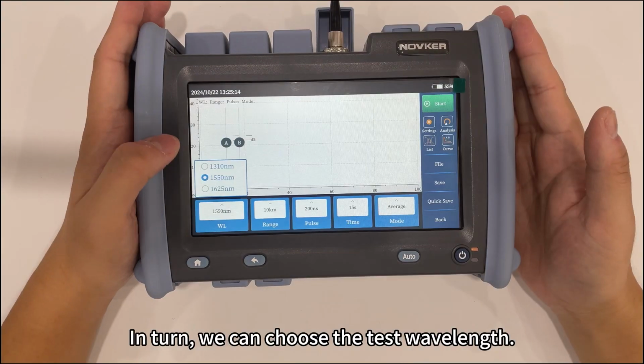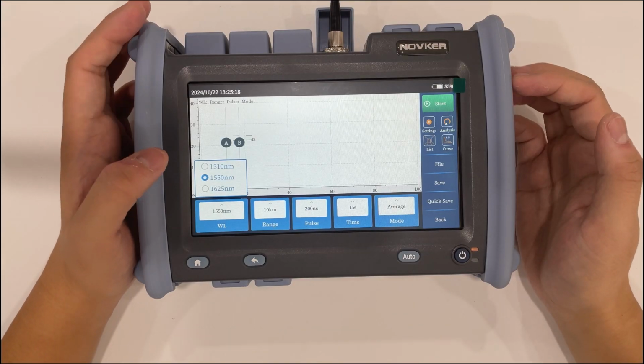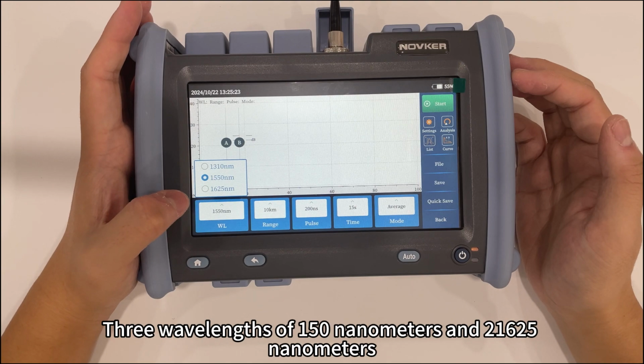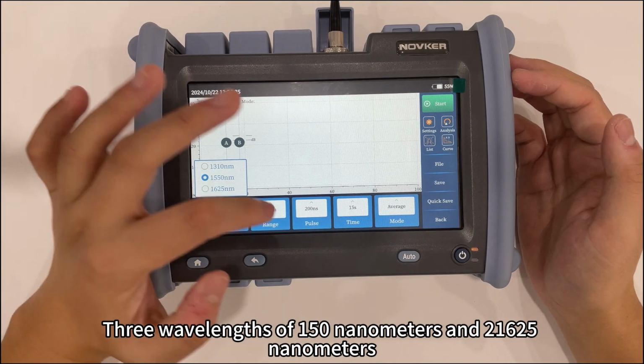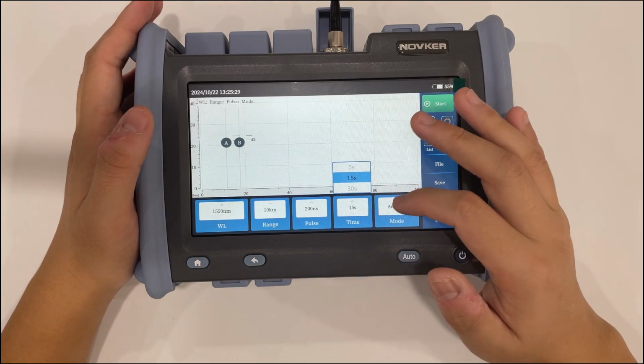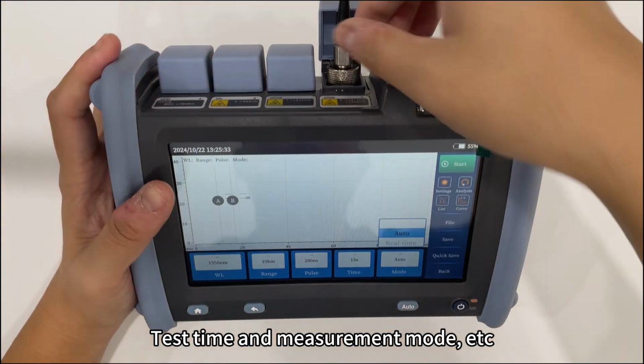The following describes the OTDR function. In turn, we can choose the test wavelengths. This device has 3 wavelengths: 1310 nanometers, 1550 nanometers, and 1625 nanometers. Test range, measure pulse width, test time and measurement mode, etc.